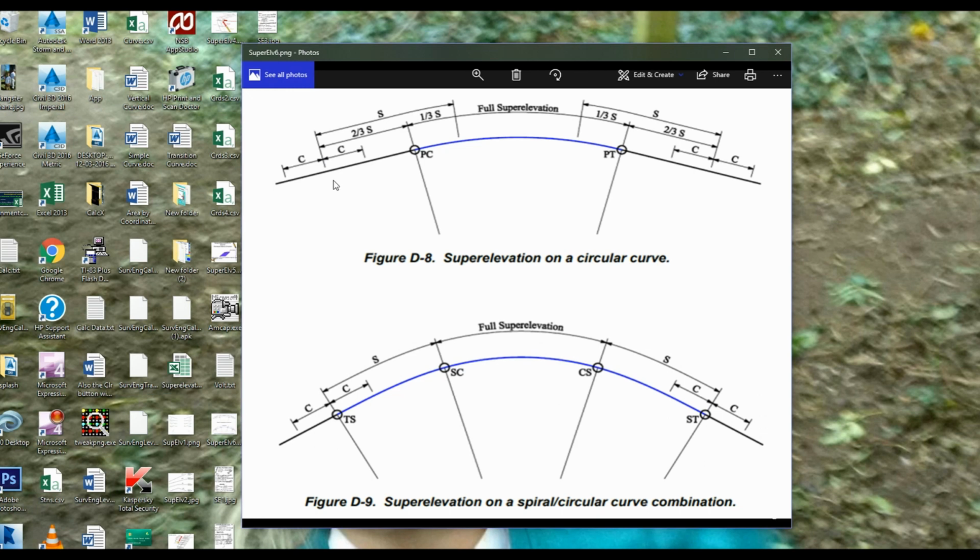So basically, that is how we would put the runoff, the run out, and the continuous crown chainages onto a normal curve or simple curve. Now what we're going to do now is just have a look at a transition curve, and it's a lot easier for this one. For the simple reason that the whole part of the curved area is fully super elevated, and we use the spiral for the runoff, the whole distance of the spiral for the runoff. So we don't need to do any calculations for the spiral because that is the runoff there either side.